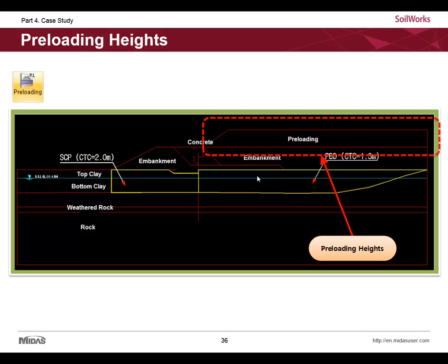And if there is some live load like traffic load on the embankment, we have to apply preload to guarantee the stability against the additional settlement after construction. So for this case, we have to calculate the optimum preloading height before construction. The main purpose is to minimize the amount of removal soil after getting target degree of consolidation, meaning that the residual settlement is within the allowable range.